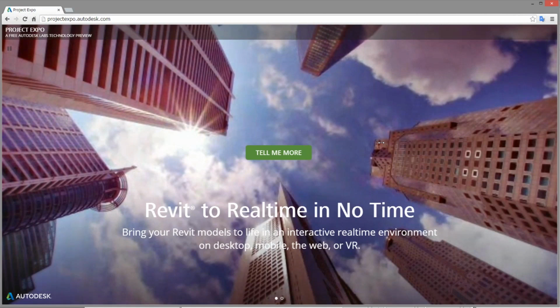If I'm using Maya, can I directly export my model to Stingray and start using the model in games? Yes, you can, very easily. All you have to do is make sure it is exported as an FBX file. And if you need the materials, make sure you check on materials. If you need to have animation, just click on animation as well. The FBX exporter will always give you these three options: model, material, and animation. If you check all three of them, it will always have all this information inside, and you can easily start using any of the engines. So that should not be a problem whatsoever.